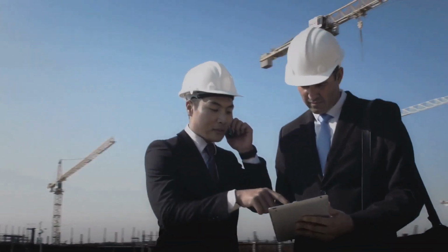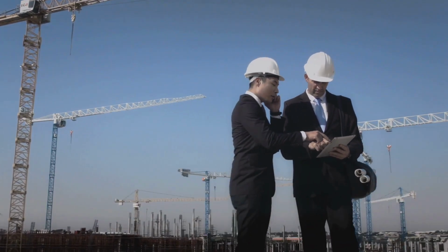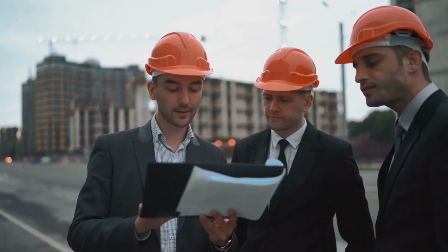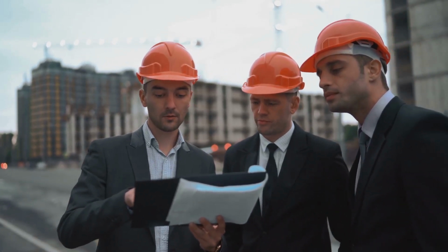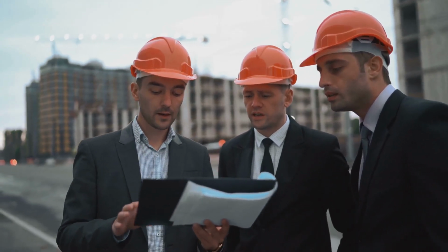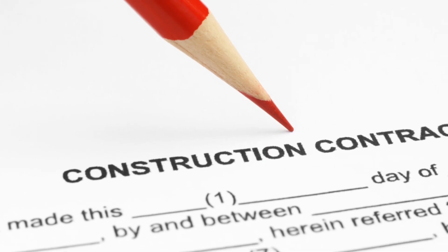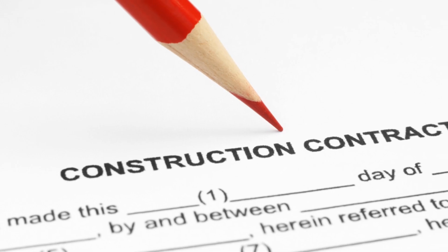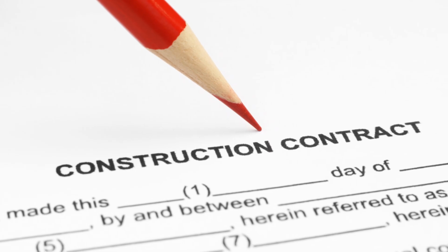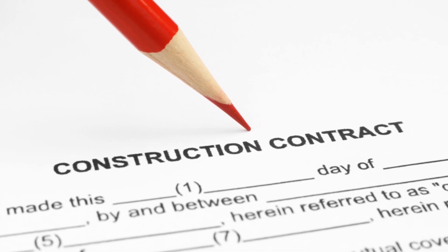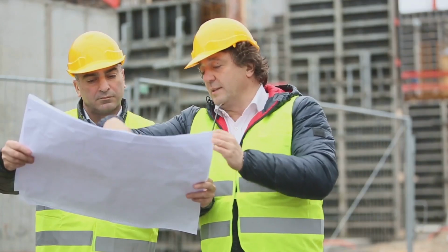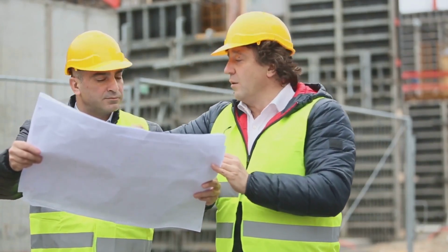DBIA serves design-build with a philosophy of high integration, problem-solving, and risk-sharing. DBIA encourages more direct and informal dialogue. EJCDC and AIA rely on formal documented communication, RFIs. In a design ambiguity, AIA, architect decides; EJCDC, engineer decides; FIDIC, DAB rules quickly; DBIA, the integrated team huddles to solve. Understanding these distinctions helps a CM adapt their management style to the contractual environment.